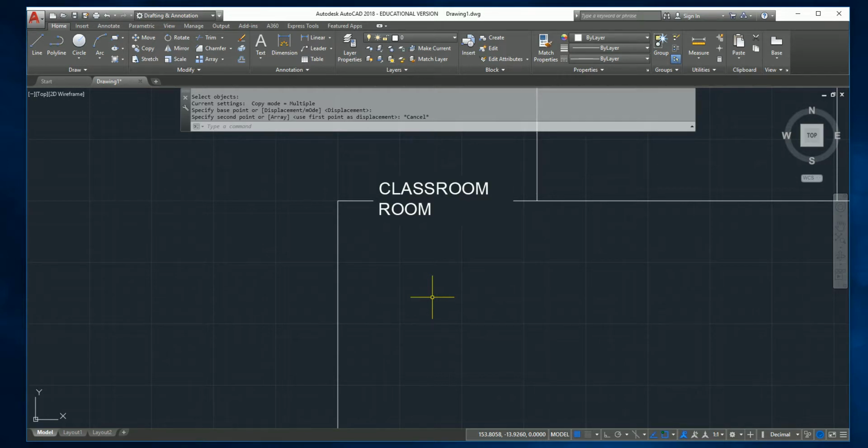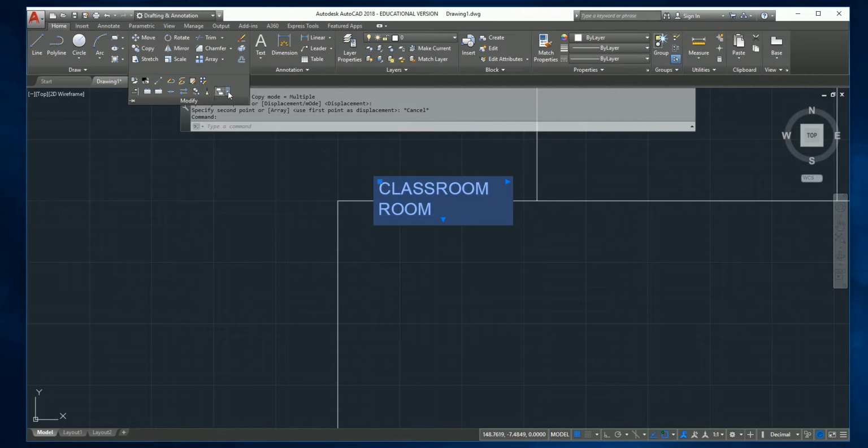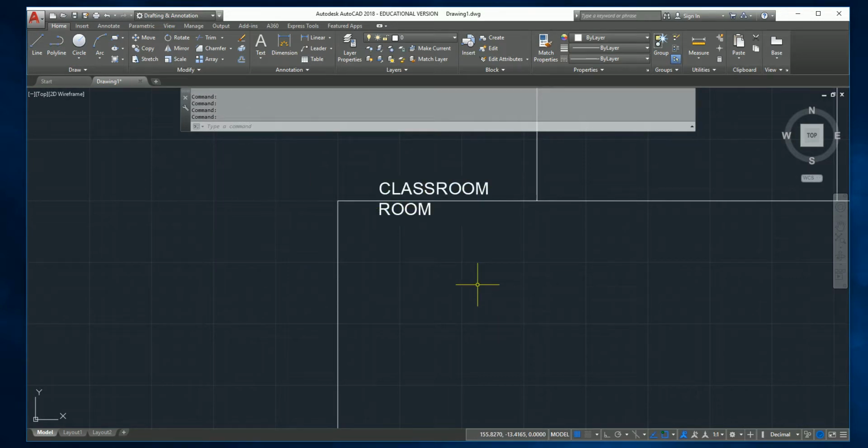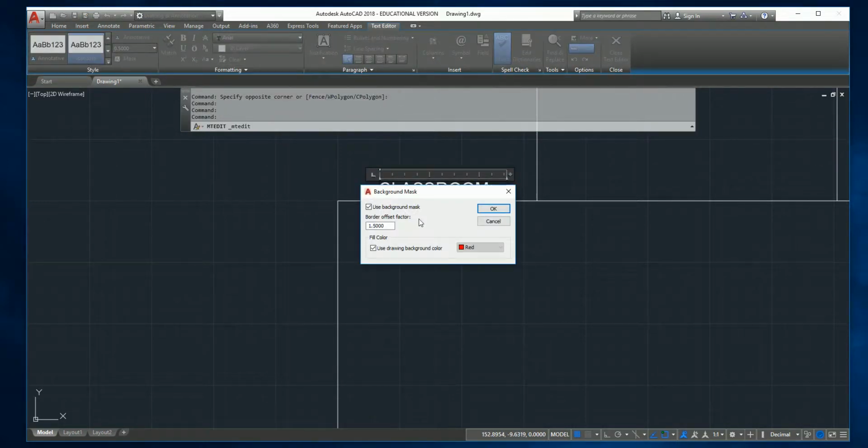Mine still shows up. You've clicked mask? Yeah. So change your draw order. Bring to front or bring in front of object. So is this showing up like that? Yeah. So if you come here and you click here and say bring to front, does it work? Did you have both boxes checked when you did mask? Yeah. There we go. So it's just drawn behind.